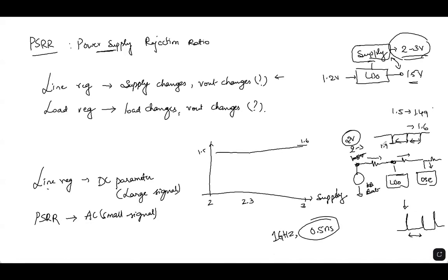So this is a voltage, the battery voltage, right? The battery voltage will have spikes every 0.5 nanoseconds, meaning you have a 2 gigahertz noise on your battery, or 2 gigahertz noise on your supply.